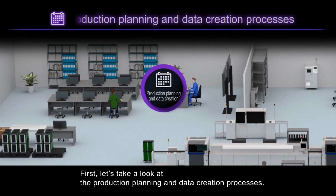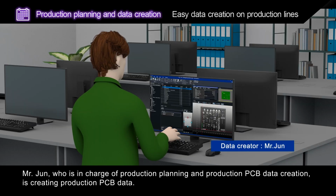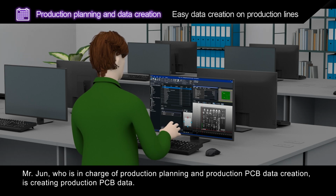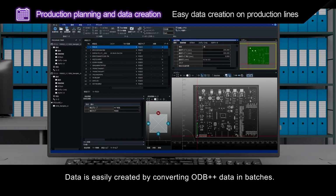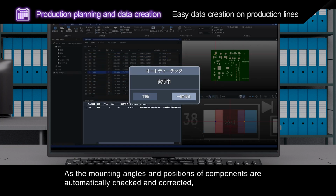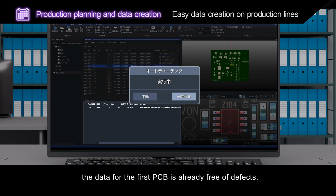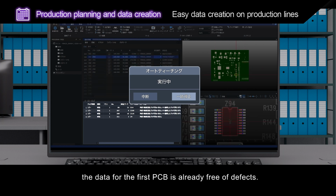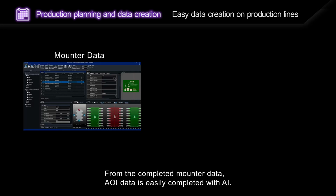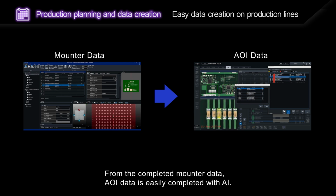First, let's take a look at the production planning and data creation processes. Mr. Jun, who is in charge of production planning and production PCB data creation, is creating production PCB data. Data is easily created by converting ODB++ data in batches. As the mounting angles and positions of components are automatically checked and corrected, the data for the first PCB is already free of defects. From the completed mounter data, AOI data is easily completed with AI.